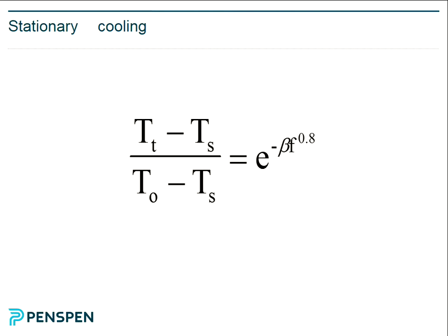So because this pipeline's buried, you can actually shut down, and it will be 5 days before the temperature goes down below the hydrate formation temperature. So you're using the fact it's buried to mitigate against hydrates. So if you can design it so all your liquid runs down into that buried bit, that gives you quite a bit of assurance under a shutdown condition. Whereas if this pipeline was exposed, it will cool down literally within hours. Within hours, you potentially get a hydrate problem.